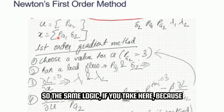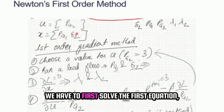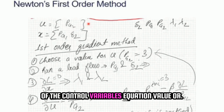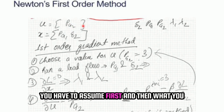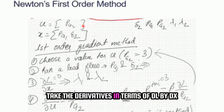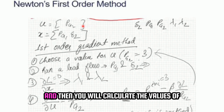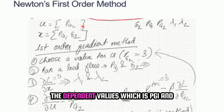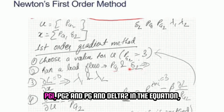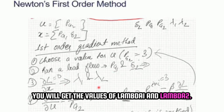So the same logic applies here, because we have to first solve the first equation, so you have to assume one of the control variables, PG2, first. Then, by assuming this PG2, you will take the derivatives dL by dx, and then calculate the values of the dependent variables, which are PG1 and delta 2. And then after putting PG1, PG2, and delta 2 in the equation, you will get the values of lambda 1 and lambda 2.